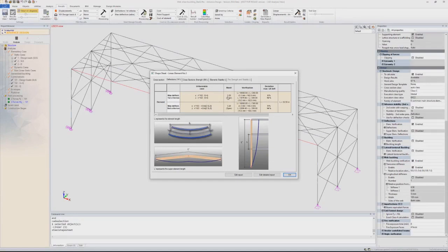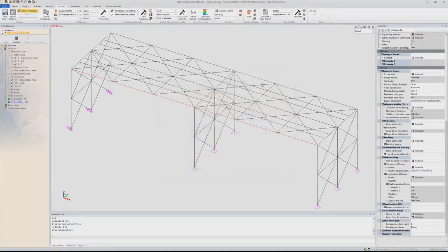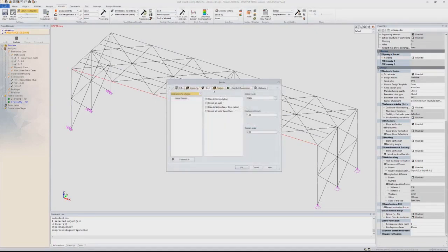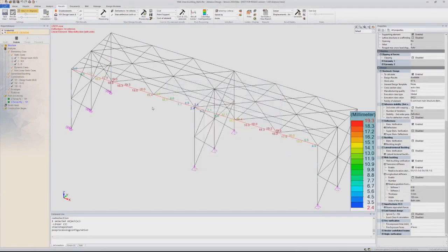And it's definitely a deflection in span, which is legit for beam. And if you want that graphically, when choosing the results, make sure not to ask for a ratio, but switch to values, and that way you will get the deflection in unit length. So here we're getting 19.3 millimeters in span, just as expected.